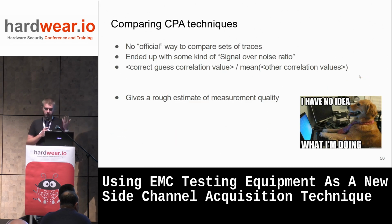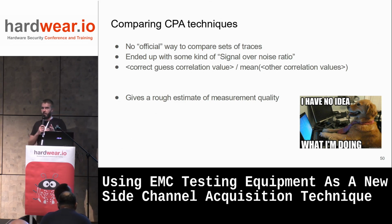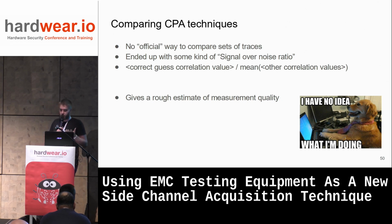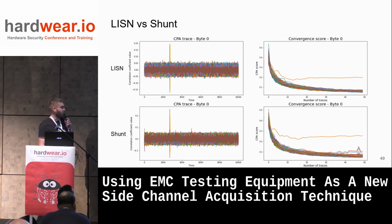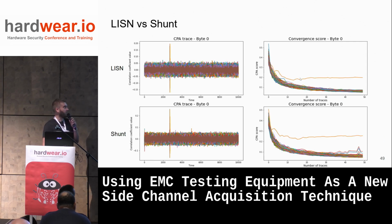So now, how do we compare this? Unfortunately, I didn't find any way to correctly compare two trace sets or techniques to discover this. So what I did is a simple signal-to-noise ratio. For a specific number of traces, I take the correlation value for the right key over the mean of all the others. This gives me a number, basically how much the correct key rises above the rest.